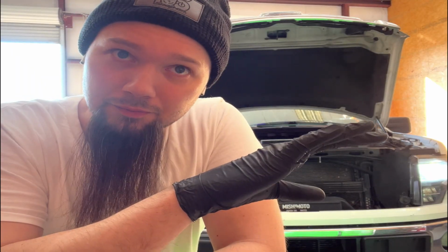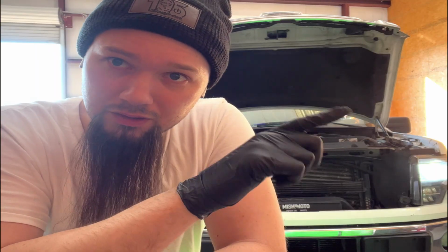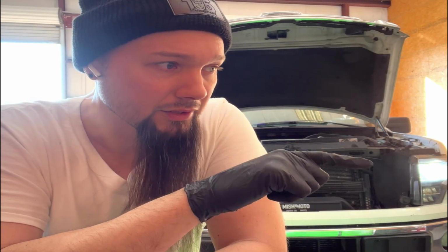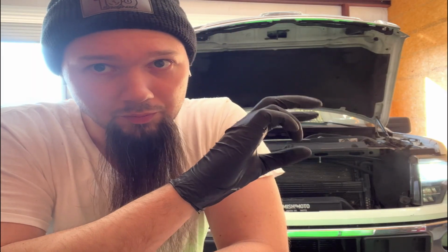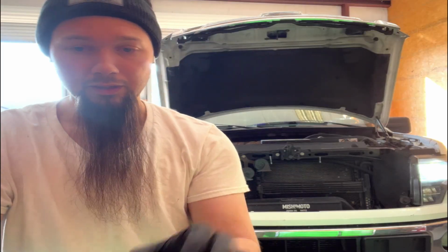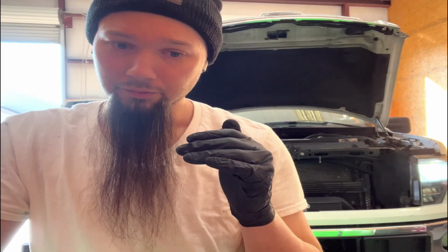When we are actuating the motor with the scan tool, clockwise, counterclockwise, I don't actually know, because the switches don't read right, what position the motor's in. At a minimum, it should have three positions. It should have a 2, a neutral, a 4 high, 4 low. And if we're just spinning that motor all the way, I questioned last night if it spins past what the table is supposed to be.